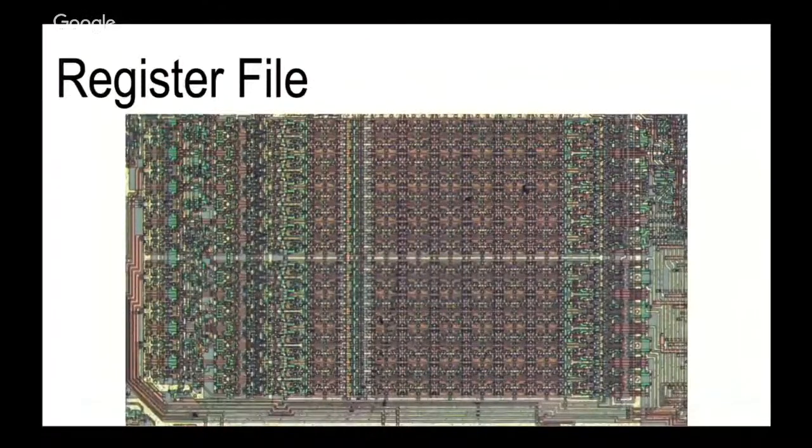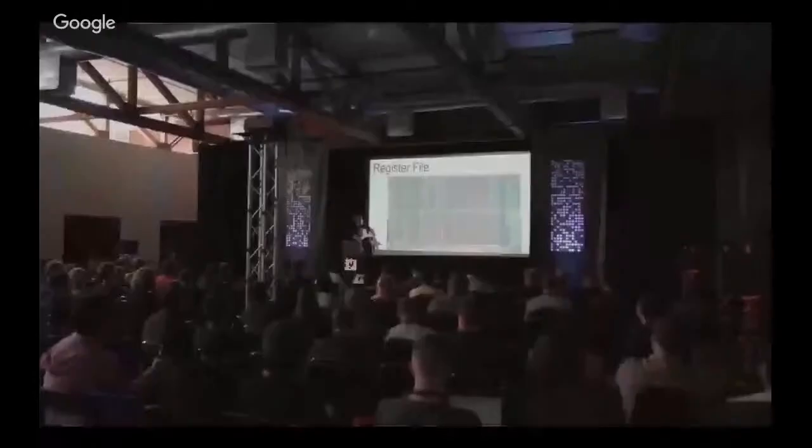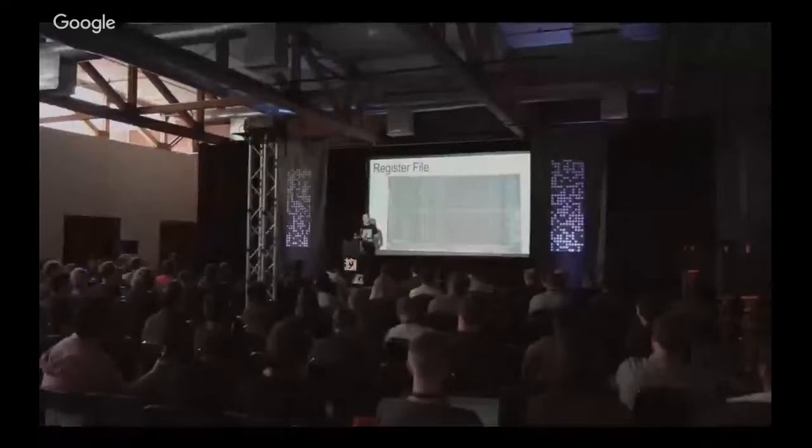Over here, we know the address lines are connected, so we can figure that this must be the program counter and the incrementing circuit for the program counter. And then the data bus is connected over here to read out the registers. If you go into a little more detail, there's some interesting things I found. There's secret registers, WZ. These are used internally for internal storage, even though they're invisible to the programmer.